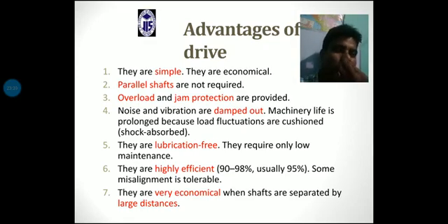They require only low maintenance. Next point is they are highly efficient. They are highly efficient, that means in the belt drive 90 to 98%, usually 95%. Some misalignment is tolerable.